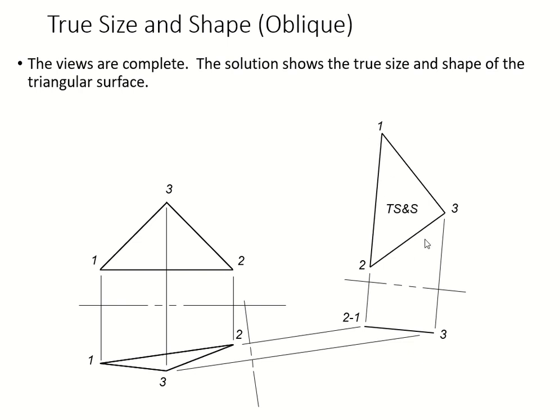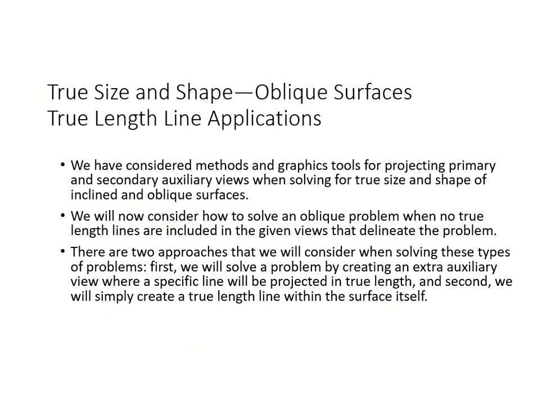And here is our projection, the last view, which is actually your right side view. Do not stop right here. Why? Because you're dealing with oblique, not inclined. Why is it oblique? Because you didn't get the edge view, can't get it, and this is not the view, this is just a projection, primary and auxiliary view. We've got to do this in order to transfer that data. You can't go from here to here without drawing this. All right, let's recap.